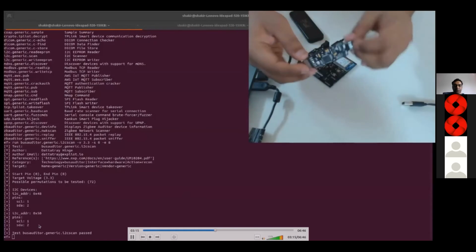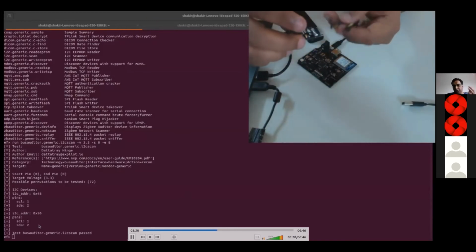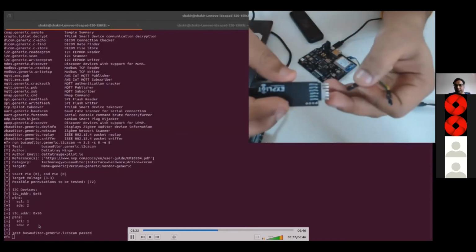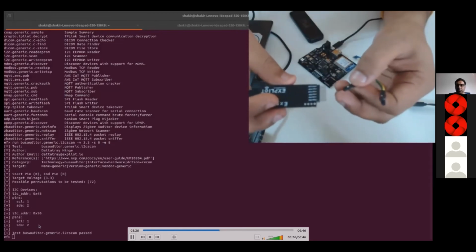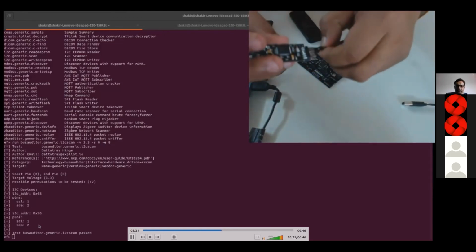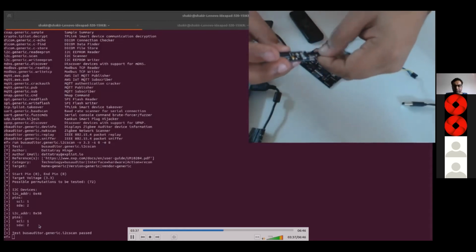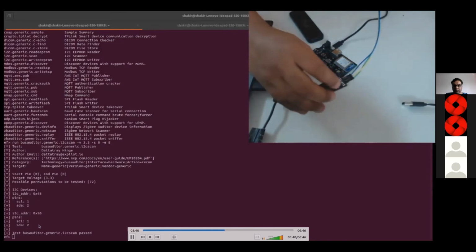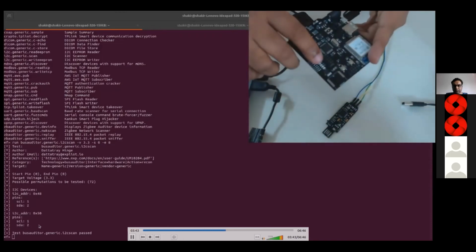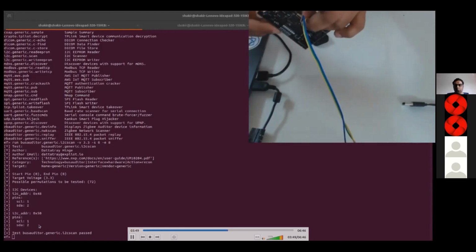Right. So we'll take now EXPLIoT Nano. Now our job is to read those I2C pins in depth and understand if we can find anything interesting. So for that we'll use the EXPLIoT Nano. There are certain pin combinations. If you go to the website and see what the EXPLIoT Nano pin configurations are, you'll easily get that. So we'll connect those pins where we identified pin number 1 and 2.